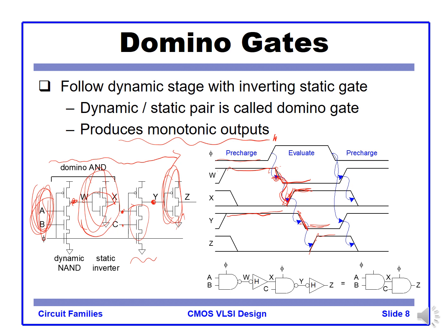In the symbol, A and B are also clocked by the domino circuit, right? We add an inverter here, and when you add the inverter, we had better use a high skewed gate inverter, because the threshold needs to be a little higher.